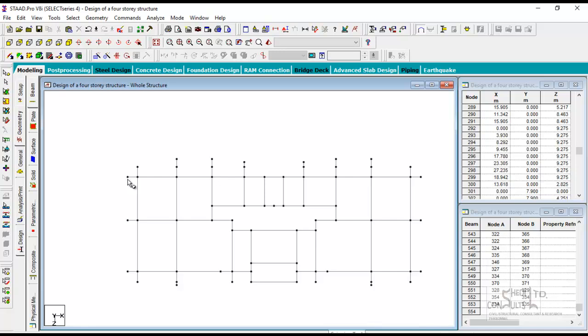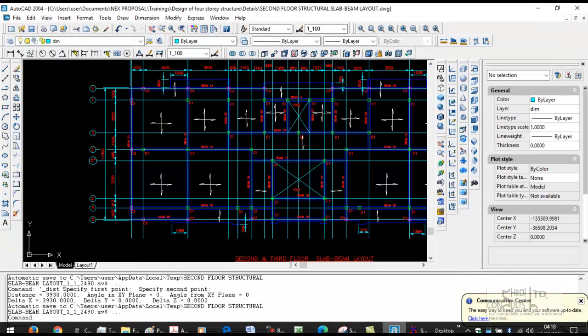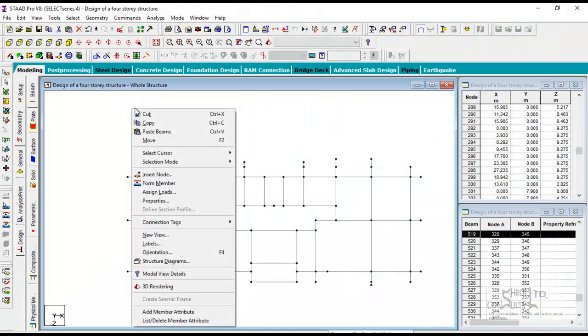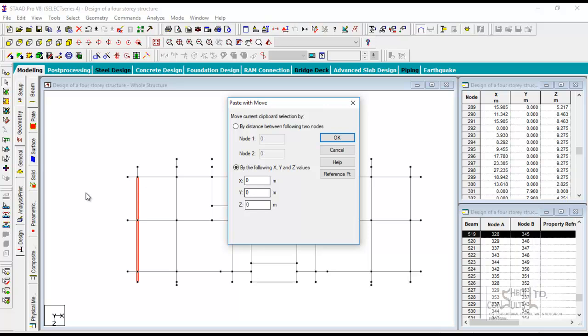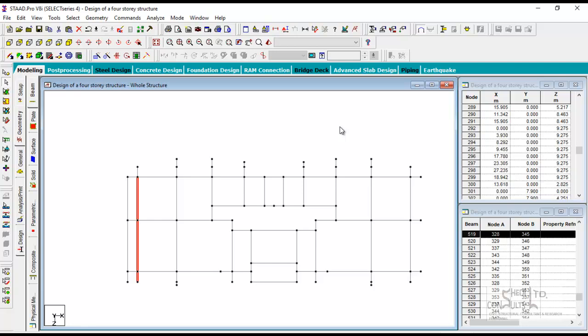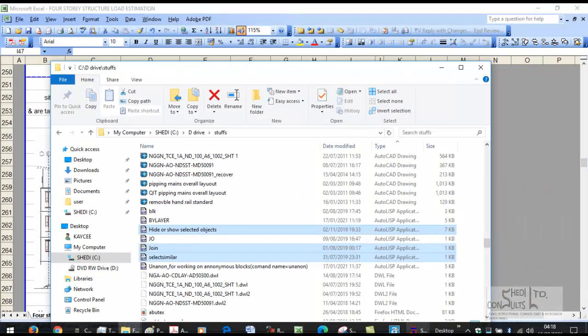Now let's ensure that the distance between this is correct. This is at x is -1. This is at x is equal to 0. So I just have to move this by -1, or copy it by -1 and later on delete that. So take this, this, right click, copy, right click, paste, negative x direction, -1, okay. Very simple, very simple.